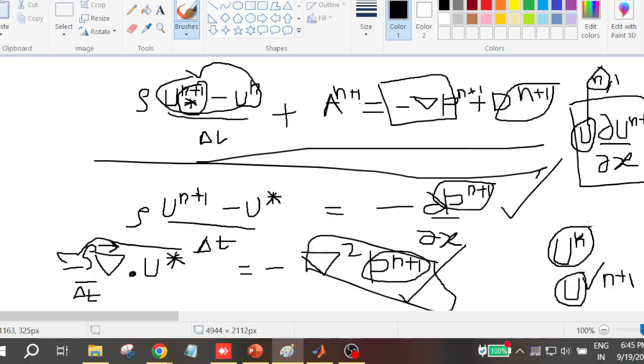We have to update the value of u and then use it again in the mass flux of the advection term. That would make it fully implicit, but let me tell you that is out of the scope of this course. So don't worry much about this fully implicit, but I hope that you have at least understood what is semi explicit and what is semi implicit method. At least those two things should be clear to you.